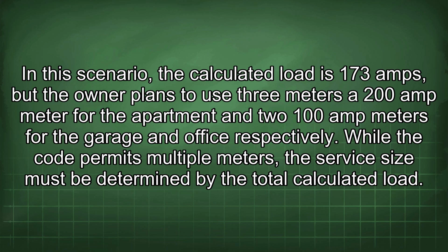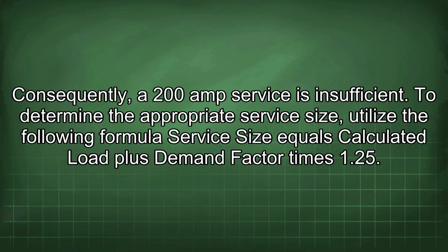While the code permits multiple meters, the service size must be determined by the total calculated load. Consequently, a 200 amp service is insufficient. To determine the appropriate service size, utilize the following formula: service size equals calculated load plus demand factor times 1.25.